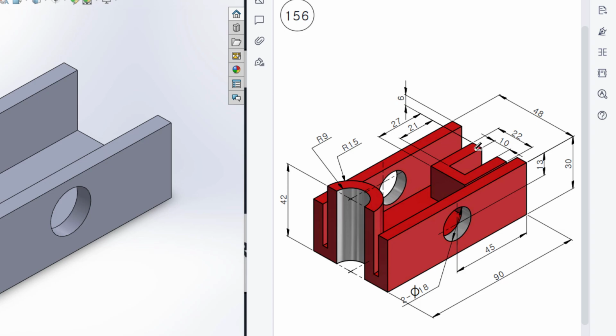For drawing this rectangular shape, first of all I will draw a center line here, and this center line will be dimension of 27 unit. Then I will use the offset entities to draw an offset of this line. Okay, and this distance will be 22 units, so the half distance of the offset will be 22 divided by 2, so it will be 11 unit in both sides. Okay, so after that I will trim all the unnecessary part, then I will get a shape like this one.